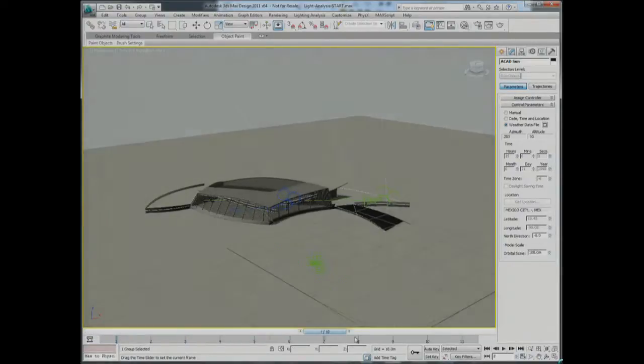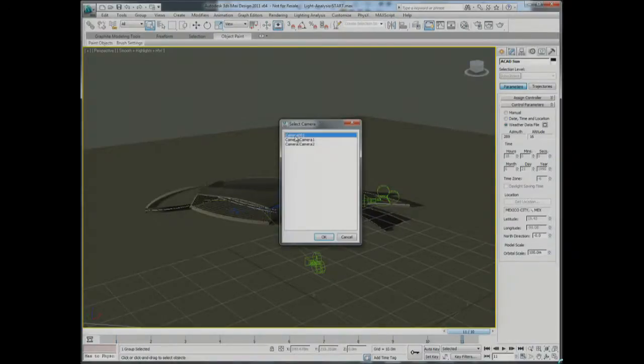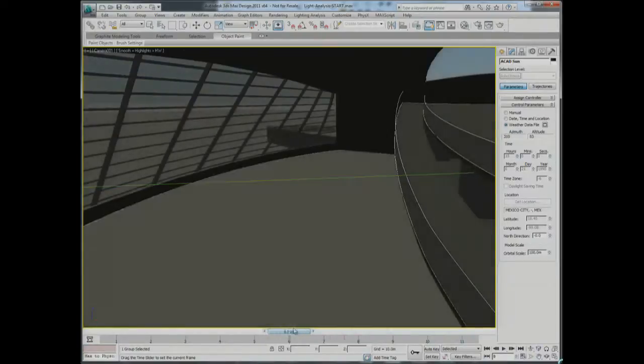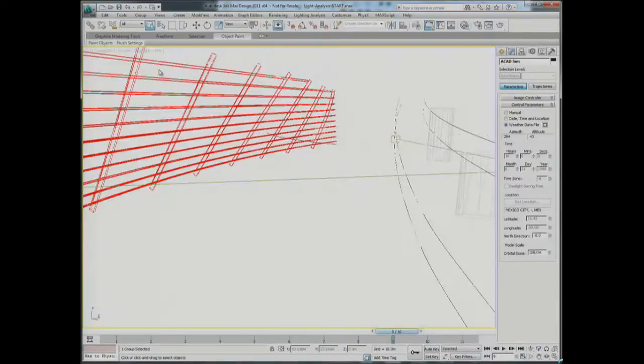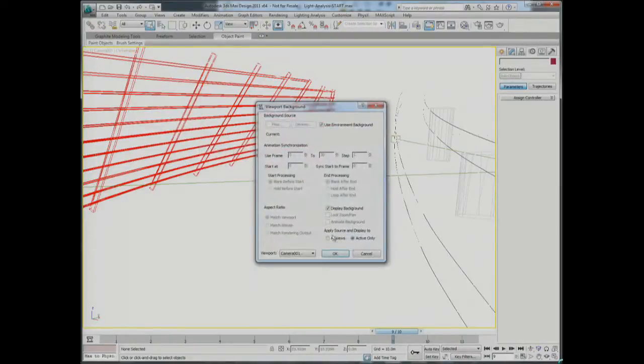So now if I move the cursor animation, I have the shadow that is being displayed at every time of the day. So let's move inside of my pavilion where I'll perform the light analysis. So you see here I can move the shadow, and I have direct feedback as well here. So I'm going to turn off the hardware shading, because when you have hardware shading and you have a light metering object when you perform your light analysis, it kind of interferes and it would display this light metering object as a shadow object.